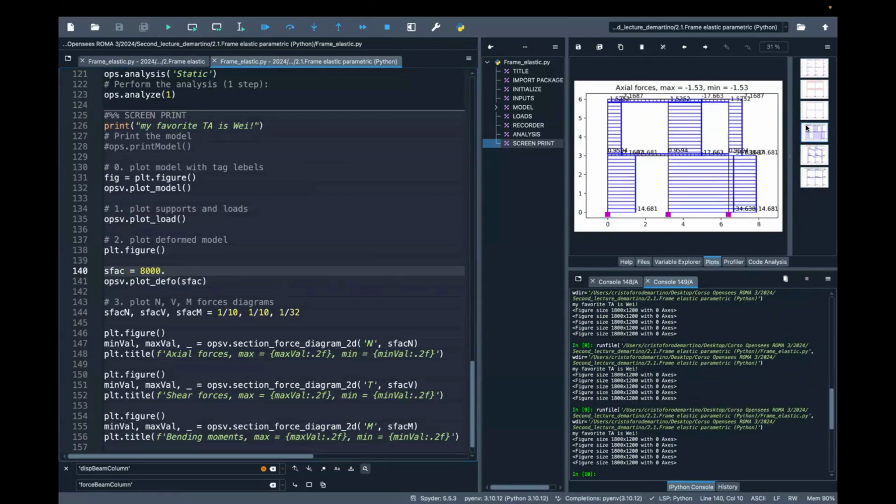Again, regarding the axial force, if you apply a certain distributed load or vertical force, the summation of the axial force at the base of each column should be equal to the total force you're applying. Again, it's the same concept of equilibrium. So those are simple checks you should always do on your model, whatever the complexity. At this point, I think you are able to build whatever frame.